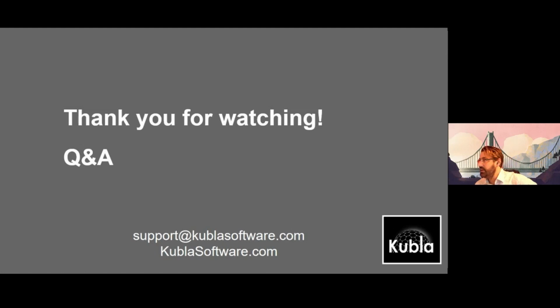So someone's asked, how large a data set can the program handle? That's a good question. We get asked that quite a lot, especially in relation to drone data. So you might have, say, 2 million points that you've surveyed from a drone. It depends quite on the power of your PC. Obviously, if you had a desktop with an Intel i9 or an AMD Ryzen 9 processor, you can handle a lot more data than a laptop. Also, the amount of RAM that you have, like if you have 32 gigabytes of RAM, you'll be able to bring in a lot more data.